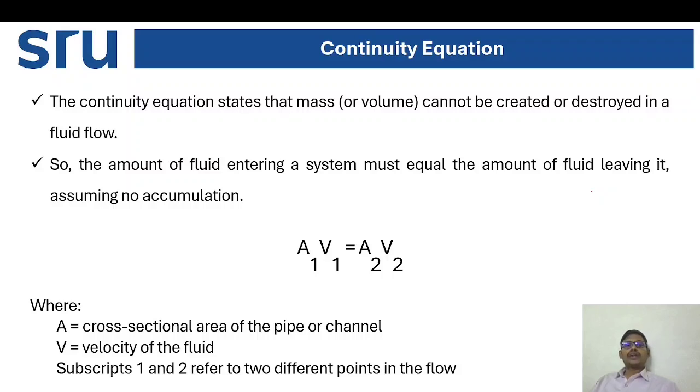Assume there is no rainfall and no addition or removal of water from that particular river stretch. Then whatever we calculate from one point to the other, this equation is valid to find, for example, the velocity at another location.